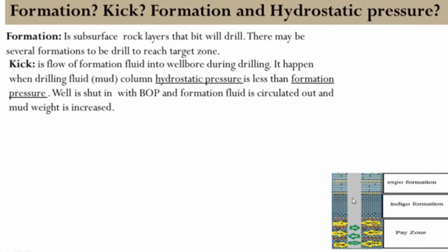To control the kick, we need to close the BOP, weight up the mud weight and circulate the formation fluid out of the wellbore. Replace the lighter mud column with the weighted mud.